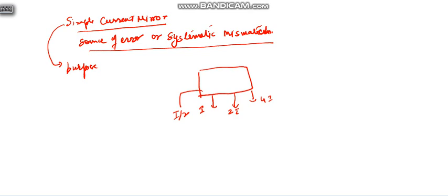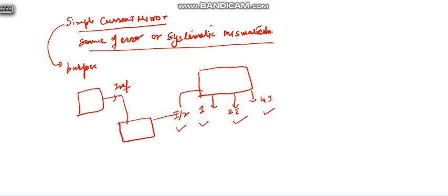With a current reference you are not going to generate all these currents, you will generate only one current, known as the reference current I ref. This current goes into the current mirror, and we are going to generate all these currents. This circuit is current mirroring.